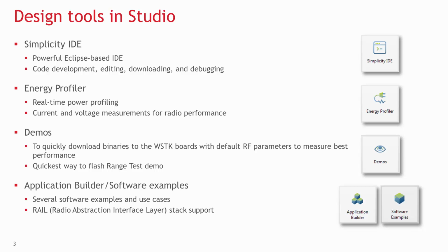The Energy Profiler enables advanced energy monitoring, which makes it possible to do power profiling of the code in real time. Also, it can be used to measure current and voltage levels for evaluation purposes whenever the EFR32 is in transmit, receive, or any other mode.